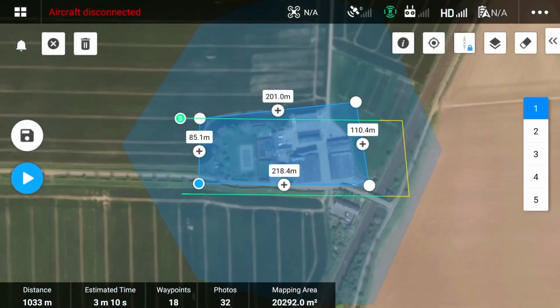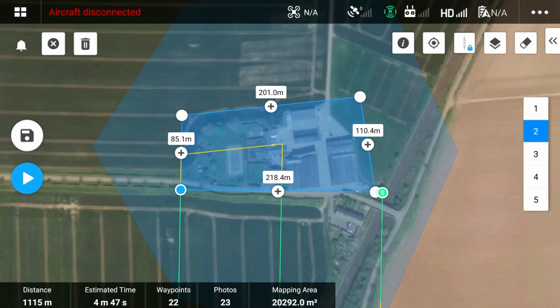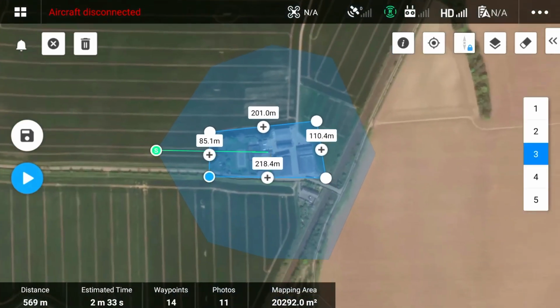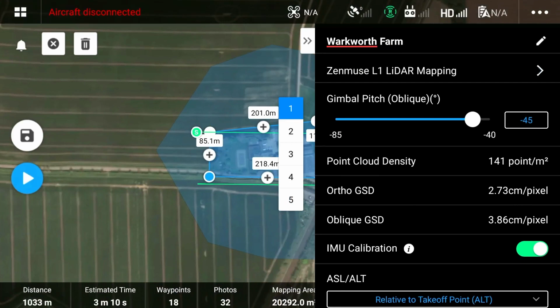This is necessary because an oblique sensor angle would essentially eclipse the area at the closest edge of the survey, and with more severe angles, less and less of the area of interest will remain inside the mission's data collection. DJI Pilot essentially considers both the flight height and sensor angle to determine how much of an offset to apply.